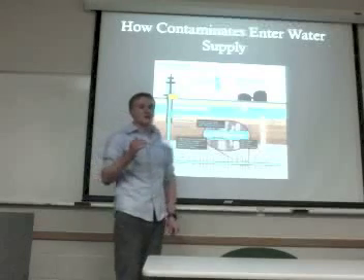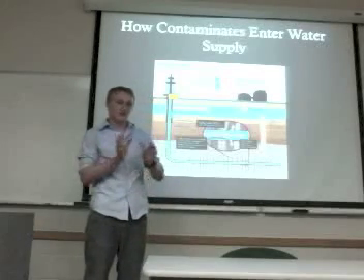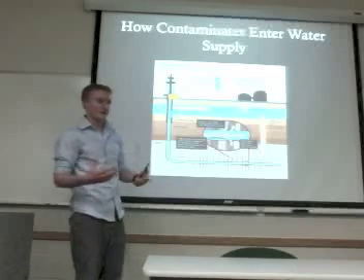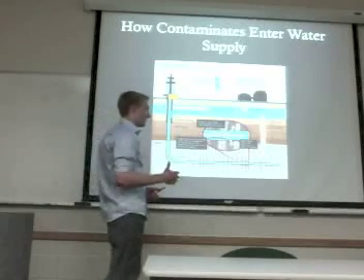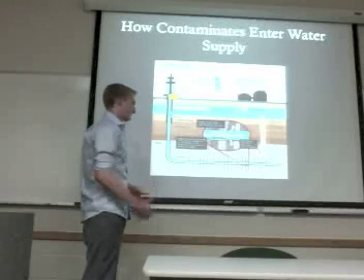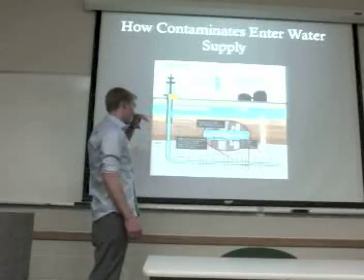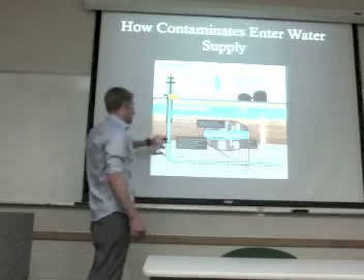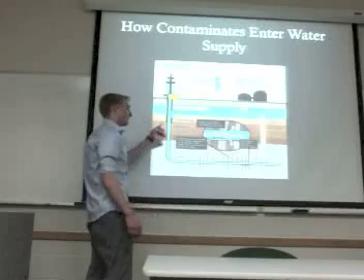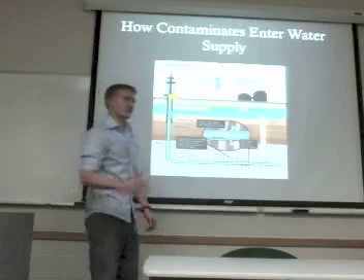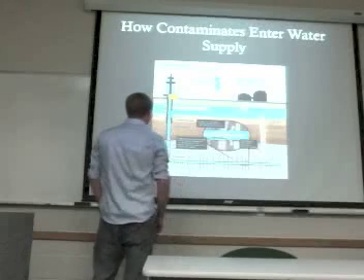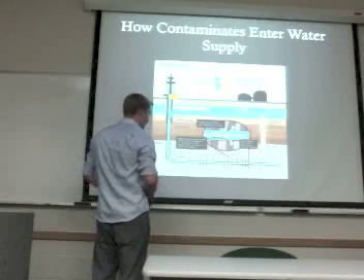Problem is, this concrete encapsulation fractures, and when you're pumping millions of gallons of high pressure fluid, even the steel can fracture. And as you'll see in later slides, not only can the fracking fluid leak into the aquifer, but also the natural gas deposits themselves can get into this water layer with drastic consequences.